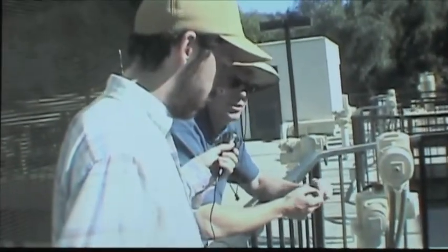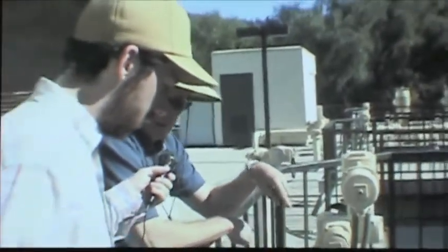And also, it's necessary for Title 22 water reclamation. Once the water leaves this plant, it's basically unrestricted use for reclamation, so you can do whatever you want with it as far as reclaiming it. But in order to make that claim, you have to have these type of filters working. Eventually, a little bit of head pressure builds up on top of it. We backwash this material back in the treatment plant and retreat it again. But in the meantime, it's going through the sand and the coal underneath here.